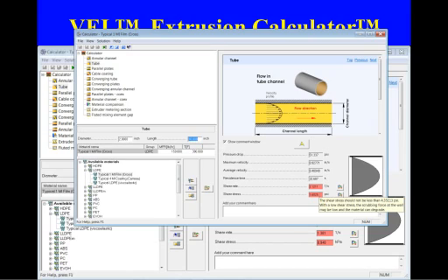With low shear stress, the scrubbing force on the wall may be low and the material can degrade. Now, that is a warning to the user saying, hey, your design condition is not very good. So the user can choose to go back and say, oh, let me try 1.75 and perform the calculation again. And we say, oh, it's still not enough. The values are still low.